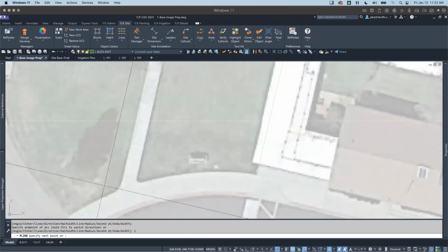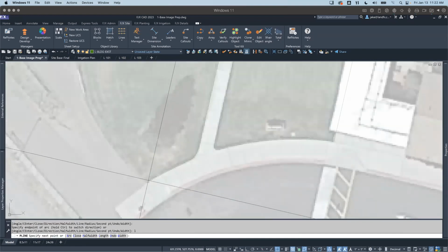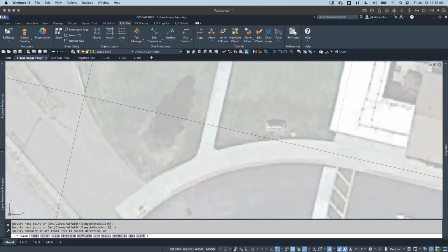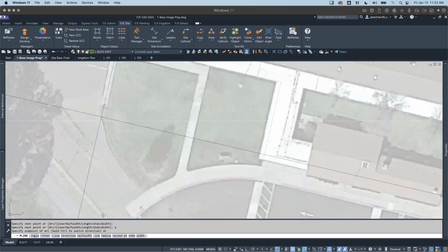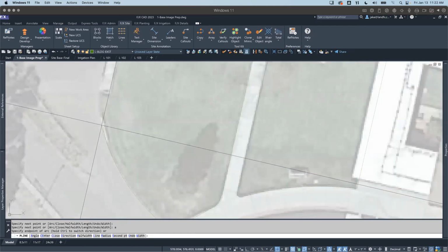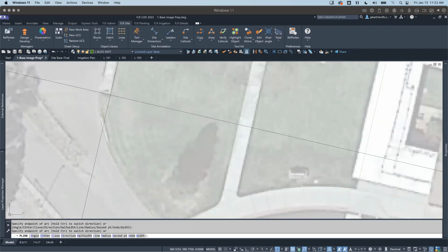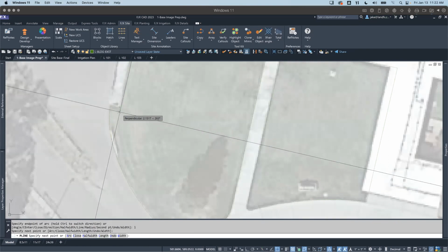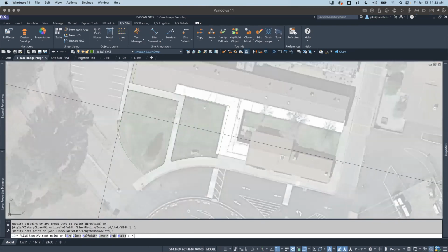And I can turn it back to a line, but that's not a line, right? That's an arc. So I can position him, turn it to a line, start coming up until it starts to get to that tangent and turn it to an arc. And we can very, very easily start finding where that arc either shifts or makes a harder angle for a different tangent there. So I can go ahead and click there, and I can finish him off to that point, go to a line, and basically close him off like that.